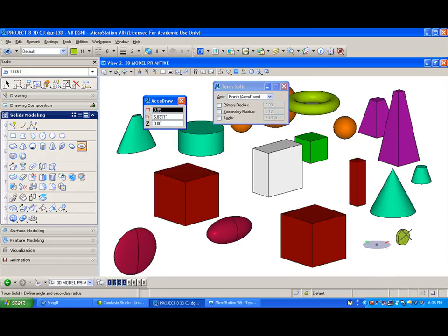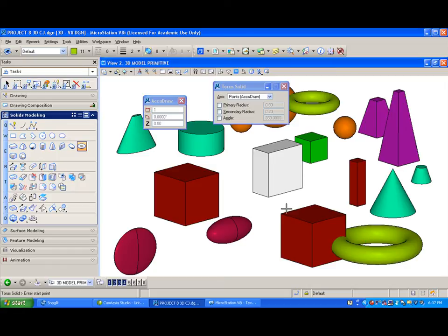See how I pull that right on the smart line? See how I get that smart line? And if that was 0.8, I'll say I want this to be 1, the distance back, right there. So there's 1, which is 0.8 plus 1, would be the radius and the direction of that second point. We can place that right in there.